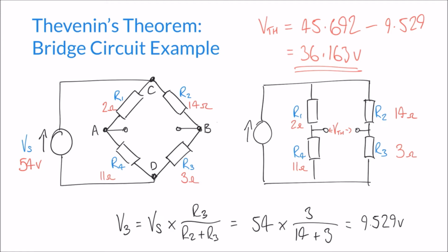So, in our previous videos on Thevenin's theorem, we said that the idea of the Thevenin resistance is to find the resistance from one terminal to the other. And that is the resistance going through the circuit, the internal impedance, as it were, from terminal, let's call it terminal A, to terminal B.